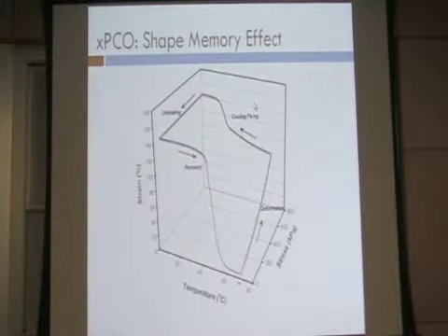If we look at quantifying such a shape memory effect, we can consider as controlled variables the temperature and the applied tensile stress and measure the strain. And what we see with a sequence of 4 loops of the shape memory effect: a stretching in the elastic state, some elongation during crystallization at stress, near perfect fixing, and complete recovery outside of that first case.